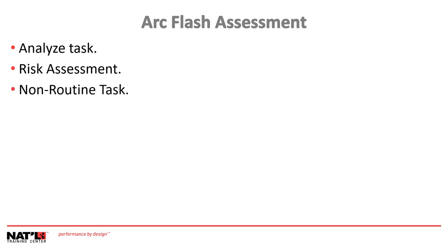Before non-routine tasks are performed in the cell line working zone, an arc flash risk assessment shall be done. If an arc flash hazard is a possibility during non-routine work, appropriate instructions shall be given to employees involved in how to minimize the risk associated with arc flash.